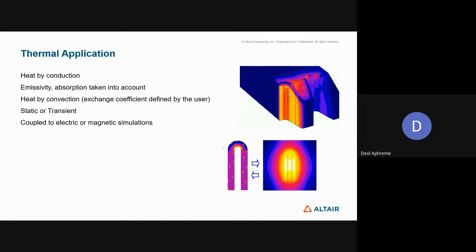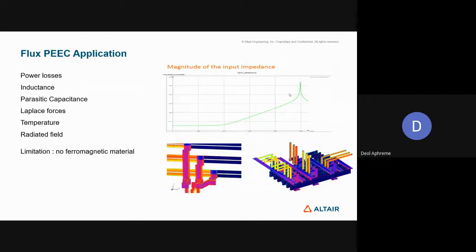So you can definitely give the convection coefficients at different regions and all of that. But then again, we call it the first level of thermal simulation. So if you're in the initial stages of your design, or of simulation, if you want to know what sort of temperatures your machine might reach, and if your design is appropriate, you can definitely go into the thermal application.